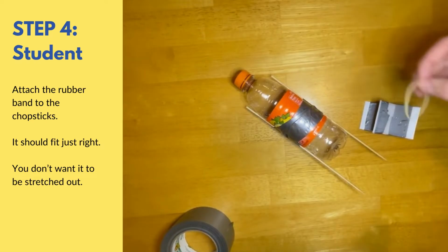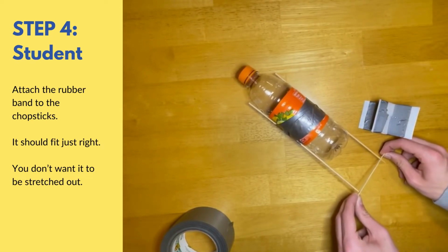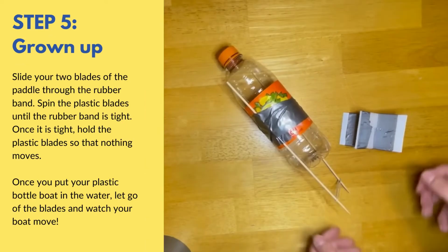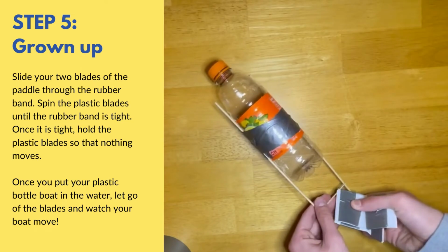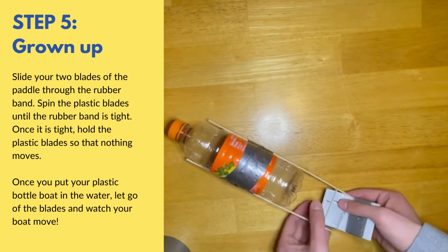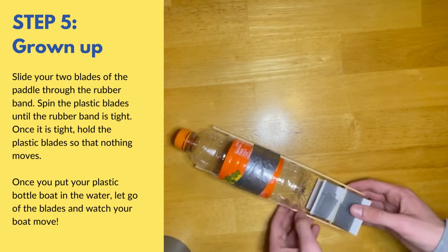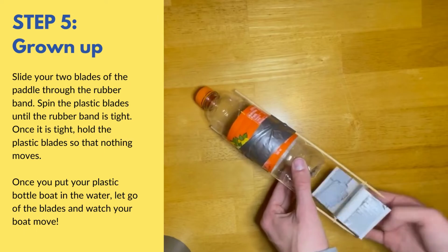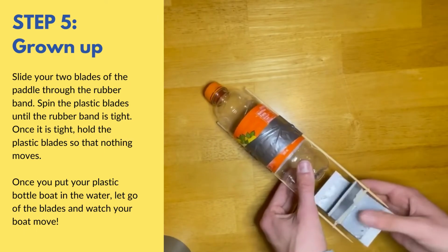Attach the rubber band to the chopsticks. It should fit just right. You don't want it to be stretched out. Slide your 2 blades of the paddle through the rubber band. Spin the plastic blades until the rubber band is tight. Once it is tight, hold the plastic blades so nothing moves. Once you put your plastic boat in the water, let go of the blades and watch your boat move.